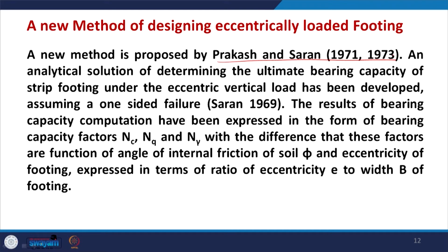So, our objective is to get the value of Qu, that is, the ultimate bearing capacity. However, the footing is subjected to an eccentric vertical load. So, that is the condition, eccentricity is there, and the question is how to account for it. Their proposed method is based on tests they have conducted in the labs and the field.